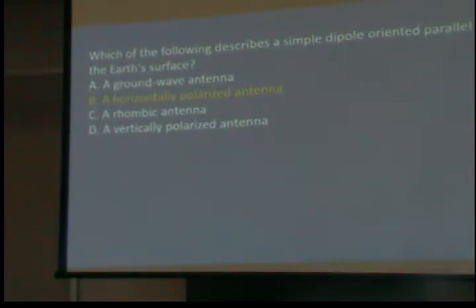By the way, one of the best antennas for HF at low cost is a long piece of wire that's set at the right length, feeding it in the center as a dipole. That's probably as good as it gets until you get into what I'm going to call exotic antennas.